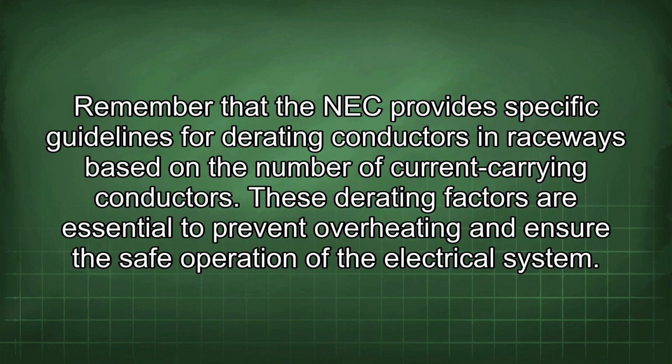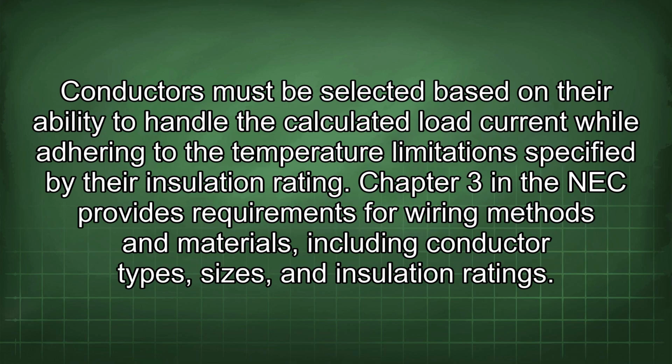Remember that the NEC provides specific guidelines for derating conductors in raceways based on the number of current-carrying conductors. These derating factors are essential to prevent overheating and ensure the safe operation of the electrical system. Conductors must be selected based on their ability to handle the calculated load current while adhering to the temperature limitations specified by their insulation rating. Chapter 3 in the NEC provides requirements for wiring methods and materials, including conductor types, sizes, and insulation ratings.